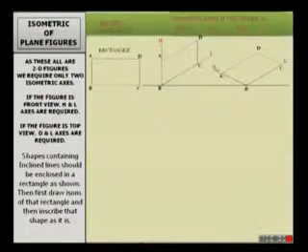Hence we know that to get the top view, we require D and L axes. So D and L will give us the top view. So A will be on the D axis. So A, B, C and D will give us the isometric top view. If there is no thickness, a simple 2D figure, we can produce it in isometric by drawing the front view and top view. It is very important to understand the basic shapes and how to produce the isometric.